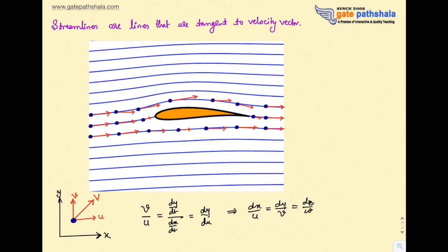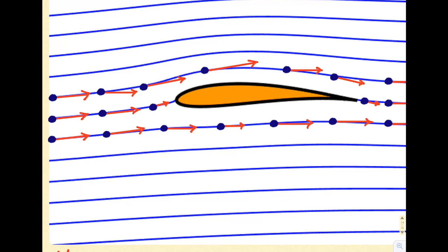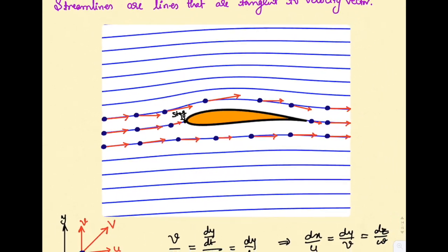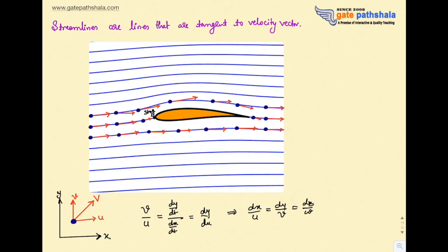Okay, so if we look at this center line, the fluid particle is coming to a stagnation state at this particular point. Okay, so here we have a stagnation state. The definition of a stagnation state or a stagnation point is the flow must be brought to rest in an isentropic manner. So we'll talk about this a little later.